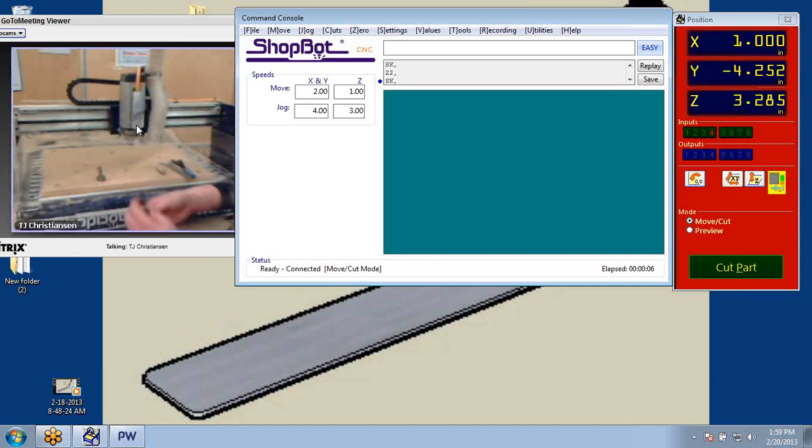Okay, since we're switching from a 1/4 inch, I have to switch up to a 1/2 inch. So I've taken that one apart. I've got this sprung back together, and this is where I'm going to start it. If the threads aren't going, give up. Check the threads. Don't force it. Don't ever force these with wrenches or anything. If they're not going, something's wrong. Step back. All right, so I got it started.